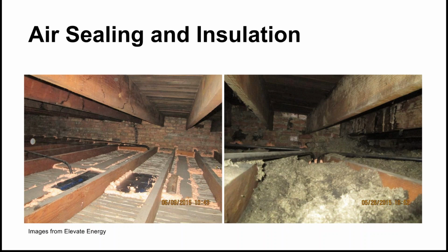But the pressure difference is a little more interesting. This occurs from a building energy phenomenon called stack effect, which is basically talking about convection of air. We know that hot air rises because it's less dense than cooler air. As it rises through a building, it will leave through holes in the attic, things like that, and it will cause cooler outdoor air to infiltrate in the bottom of the building to replace it.